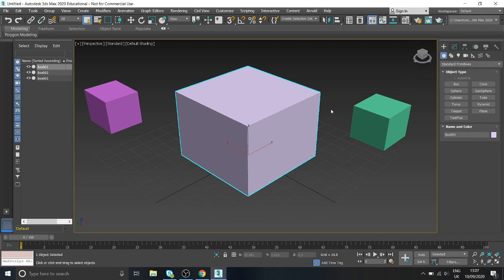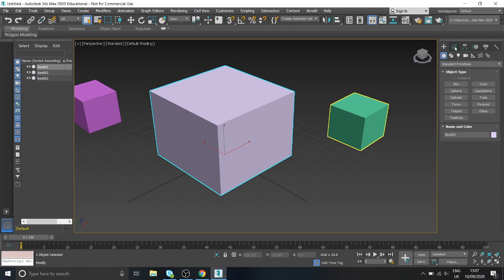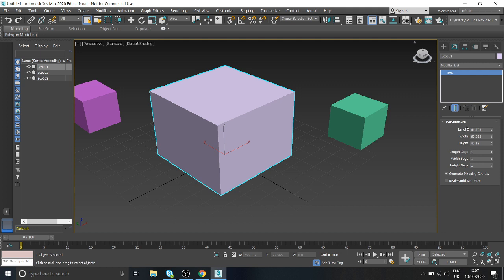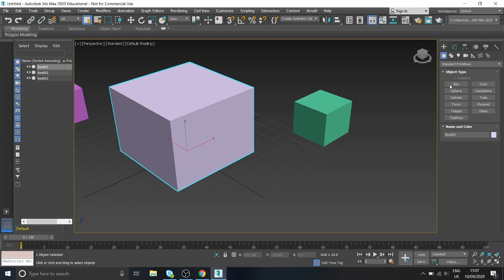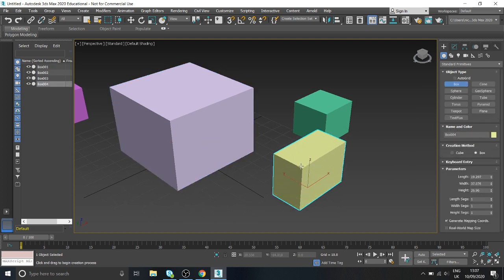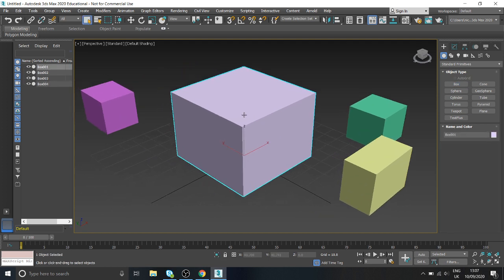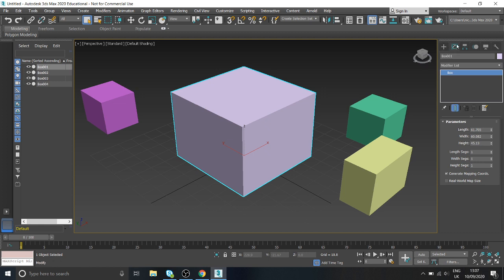and what you'll need to do, if you come over here, this is the Create tab, this is the Modify tab. So I go to the Modify tab, you can see the parameters of the shape. Just a quick note, if I created a box like this, as soon as I've created it, you do actually get the parameters here as well, without having to go into Modify. So they're just the parameters, but in 2 different locations, depending on when you're accessing it. So if I were to right click that, and I want to get back into the parameters again, you need to click up here and modify.